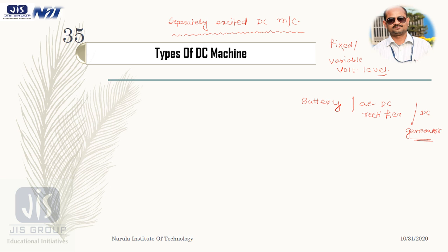It is not enough only to obtain the DC current, but our motto is to control the field current. That means the field current also must be controllable, so that the magnitude and direction of the magnetic field produced can be controlled as per requirement.